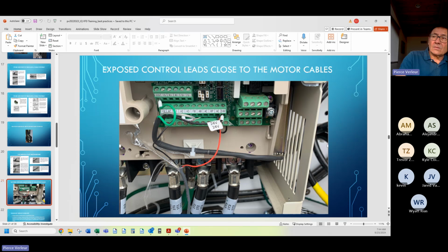And this is our drain line and our shield, and it doesn't look like it is in the original design of the cable. In many cases, guys will twist it up and then put a heat shield on it for neatness and then put a nice terminal at the end of it. Unfortunately, when you twist up the shield, you change its impedance.